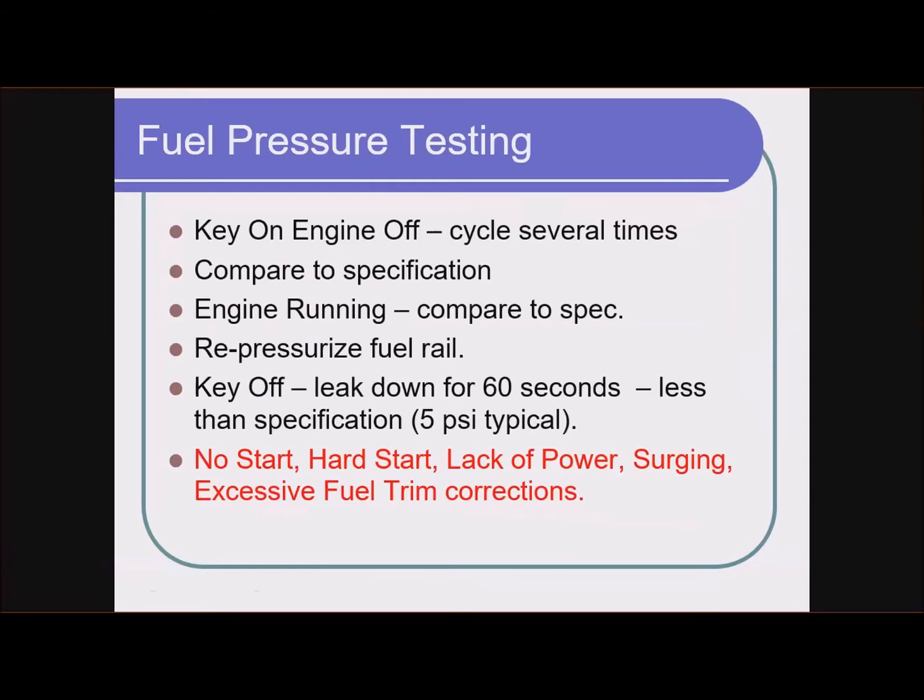If our fuel pressure is too high, we could have the opposite problem. Every time the injectors open, they spray too much fuel, so we're too rich. And so we'll see negative fuel trim numbers as the computer tries to take fuel away to get it right.